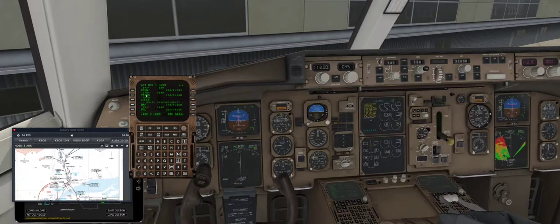There's a discontinuity between the end of the departure and the beginning of the arrival. Well, we're actually not going to fly anything in between those, so we're going to remove that discontinuity just like you saw me do. And now we hit execute. We don't have any discontinuities, and we're good to go.